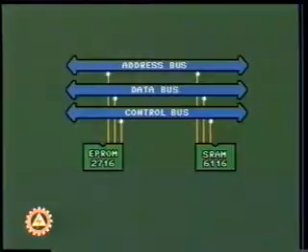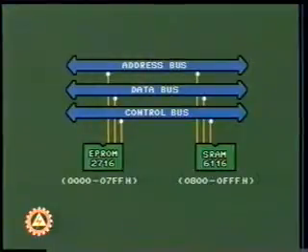The memory map for EEPROM is 0000 to 07FF, since the program counter of processor is cleared to address 0000 whenever the system is reset. However, memory addresses for SRAM are 0800 to 0FFF.